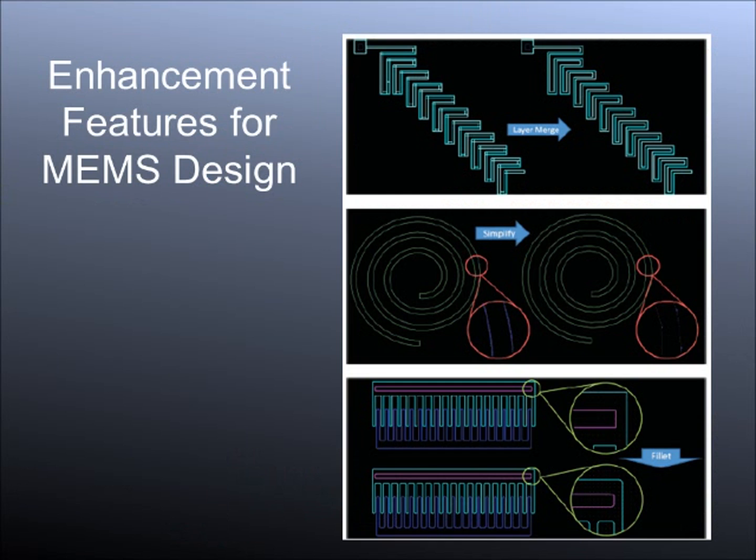And within Blueprint, we have several drawing tools that are tailored specially for MEMS. Here we can see the Simplify tool, which makes it easier to mesh your 3D model that you generate from your mask. And you could also add fillets right from within Blueprint.